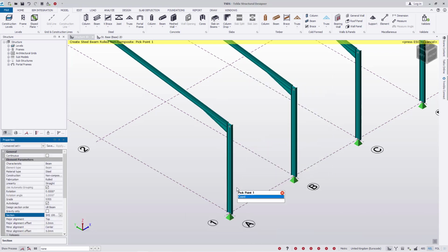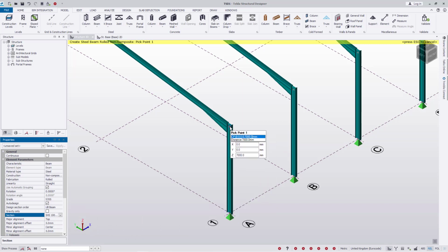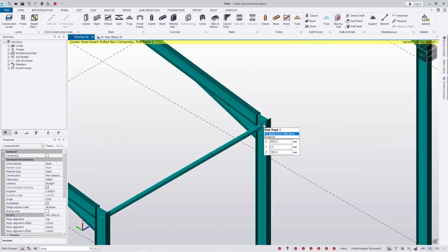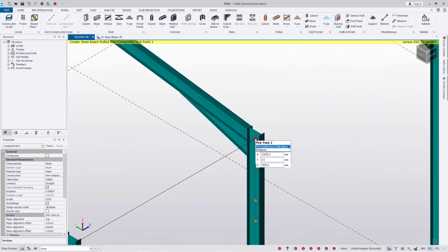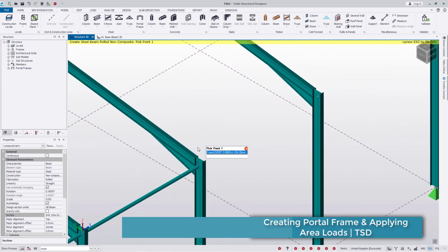I'll click select. So you realize the moment I mouse over this, Tekla Structural Designer is able to identify the snapping points at quarter distance, third distance, and midpoint, and at midpoint of this height. So let me just define it from that spot and move all the way to that spot, and begin another one from that spot and take it to that spot. Start another one from that spot and take it to that spot. So let's first of all define this. Place tie beams here.